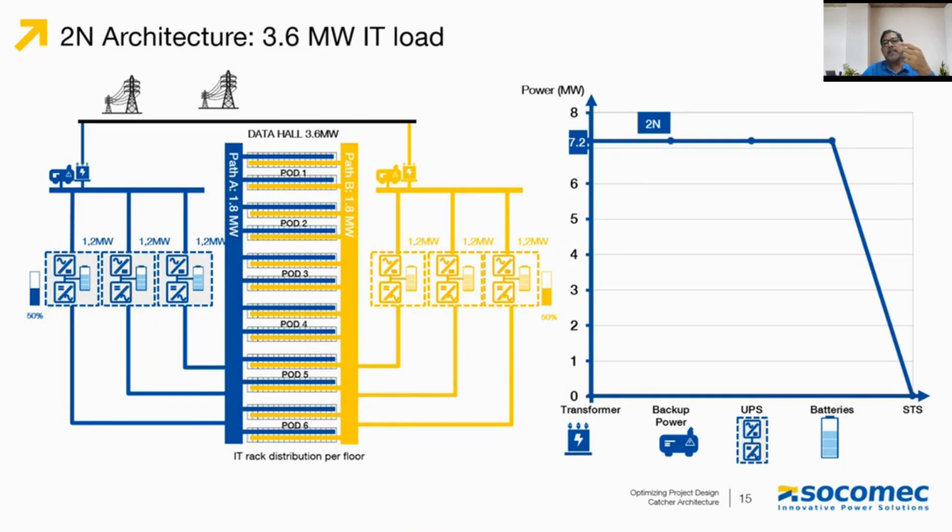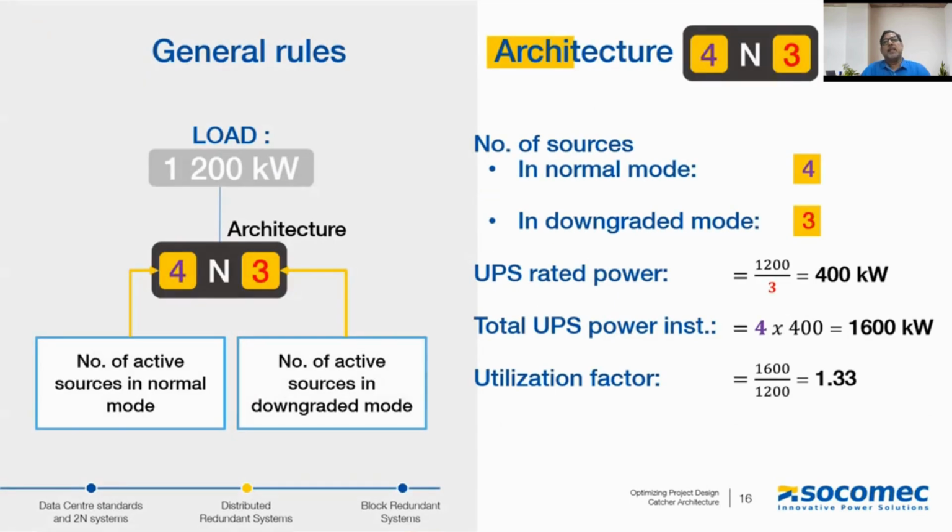The related infrastructure to these UPS systems, like the upstream transformer and the backup power, also needs to be sized for managing these two identical loads. So obviously, the ratings of this transformer and backup gensets also have to be aligned equal to the required capacity of the UPS.